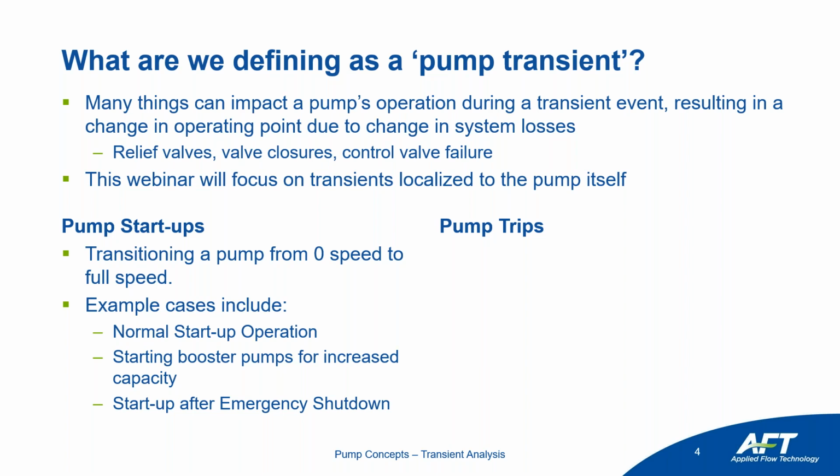The final case is you can have a pump startup or kind of a restart event, and that could happen after an emergency shutdown or something else like a power loss, anything that can cause a pump trip. So if a pump startup is starting up from 0 to full speed, pump trips are the other side, where you have your pump in steady state. Something trips, maybe power to the motor is lost, and now that pump is no longer creating that pressure and that driving force, and so it'll go down to 0.